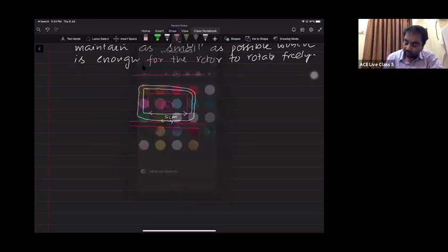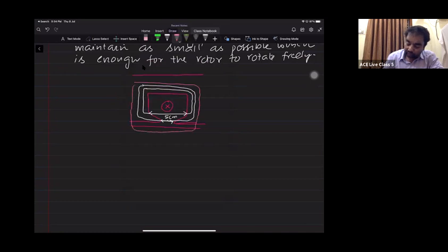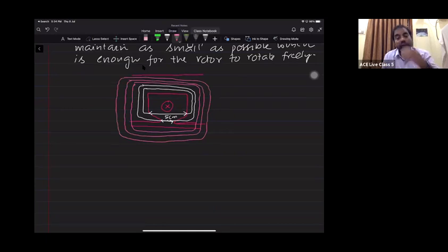So what is the other way? The remaining flux lines will try to take the 2 mm path like this. So these are called... like this, you can see. Here, when the slots are partially closed, the leakages have increased.